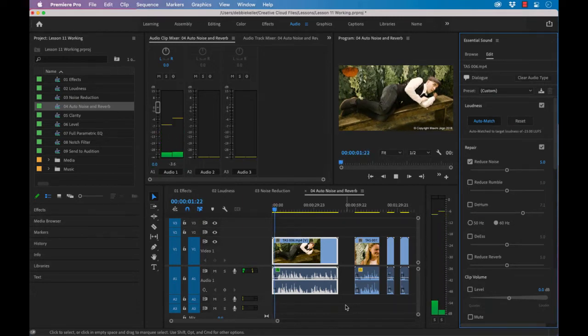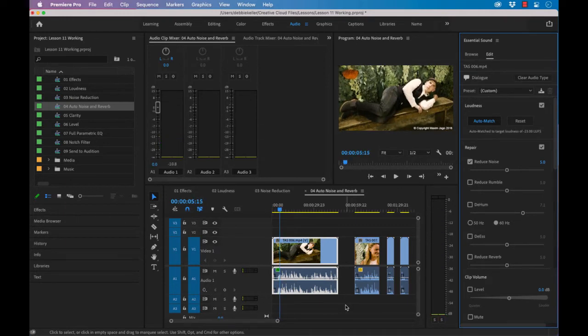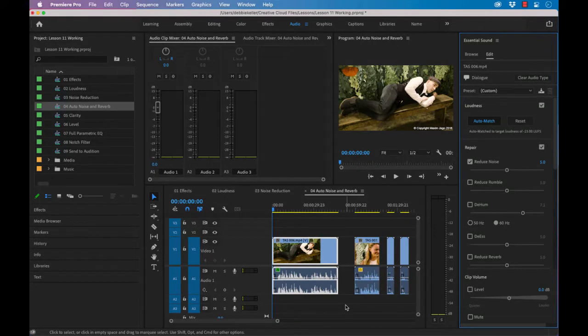The loud rumble that begins at about 00001000 is immediately much quieter. As with many effects, trial and error will usually yield the best results. Try adjusting the effect intensity during playback. If the effect is too strong, speech might begin to sound distorted. If the effect is not strong enough, too much of the unwanted background sound might remain. When you have finished experimenting, leave the setting on 5.0.